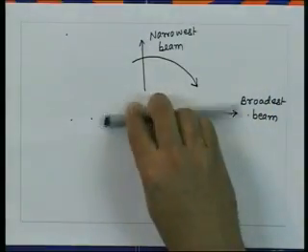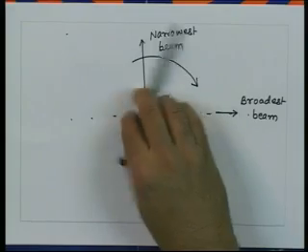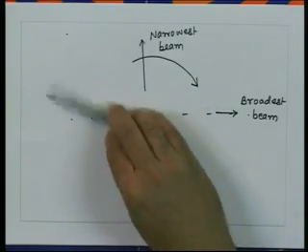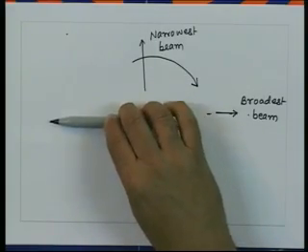So, the purpose of the phased array antenna is that without physically moving the antennas, if we can control the phases electronically, or if I change the progressive phase shift of the antenna array, then the direction of the maximum radiation would change and the beam would scan, maybe from horizon to horizon, depending upon how much phase gradient you put on the array.